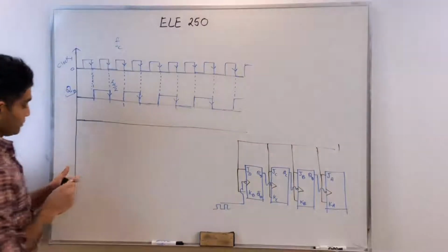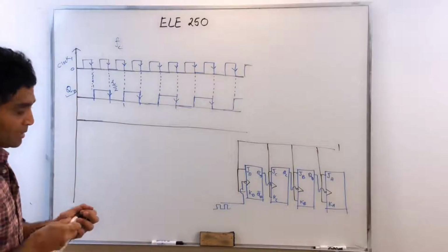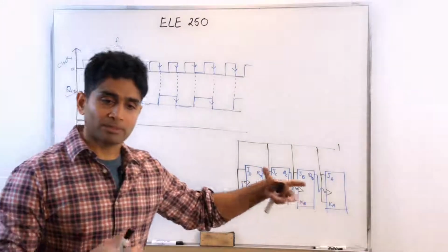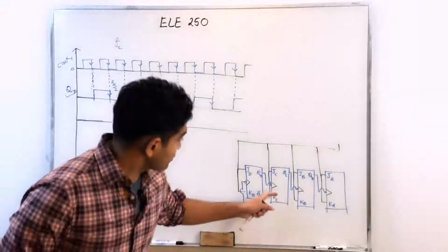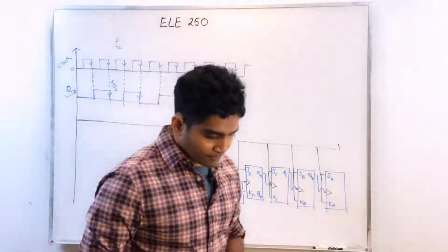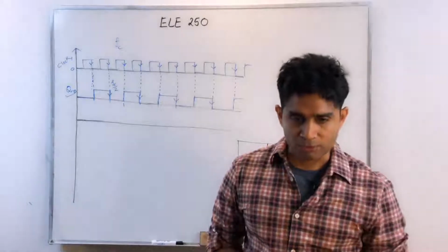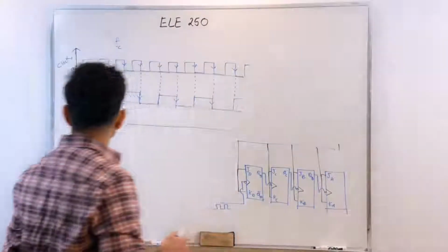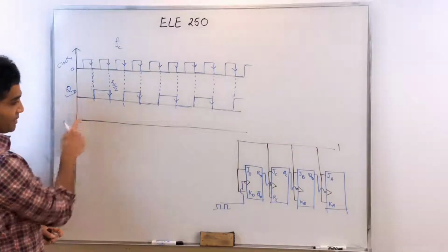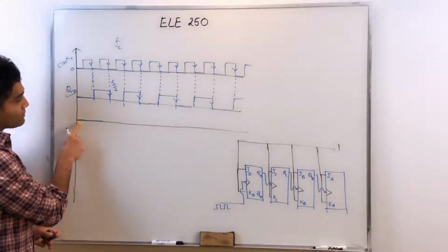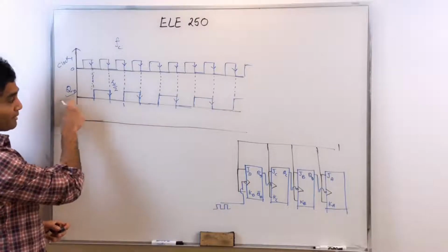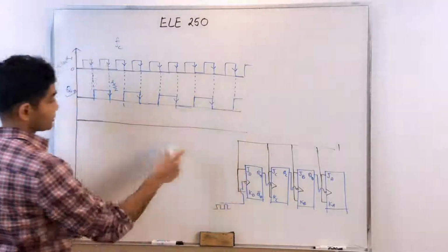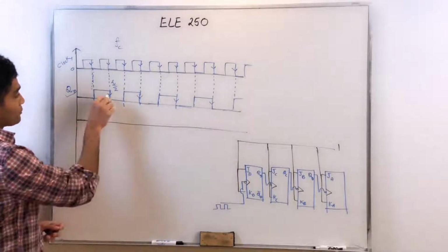All right. So I'm going to plot QC. Again, my QC, the JC KC flip-flop, is configured in a toggle state. So if I assume 0 to be the initial state of that flip-flop, it toggles at every active edge of this clock, the QD clock, because that is what is being applied to JC and KC. So this is my active edge.